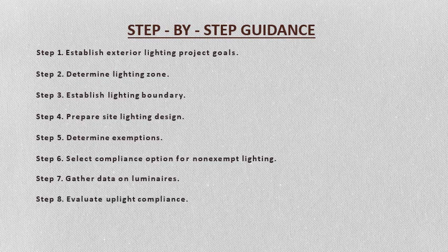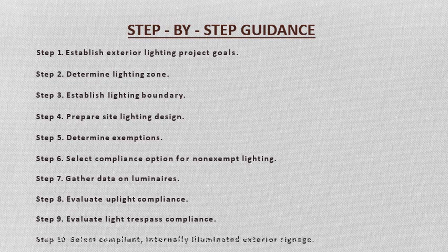Step 8. Evaluate uplight compliance. Determine compliance with the uplight requirements and make any necessary adjustment to the preliminary lighting design. Step 9. Evaluate light trespass compliance. Determine compliance with the light trespass requirements and make any necessary adjustment to the preliminary lighting design.